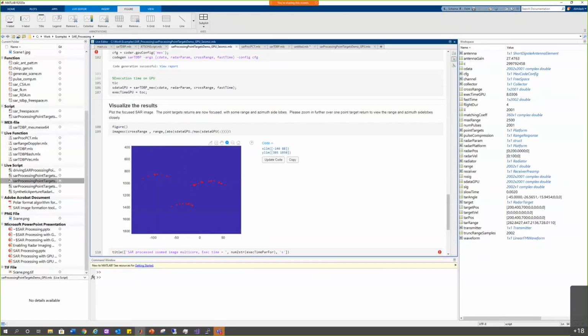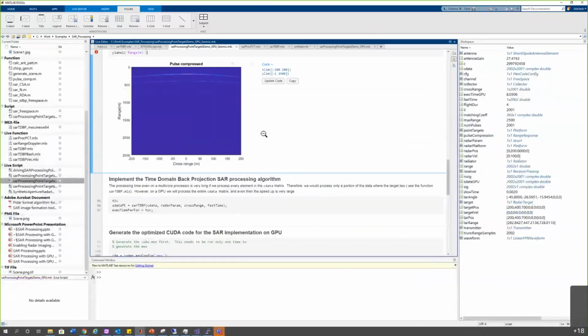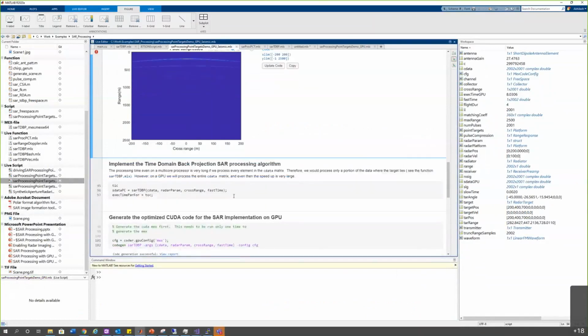And then I will apply the phase compensation for the data points, which is my signal, and then add them up. So that's what's happening. So add them up, add them up, add them up. So that's why when I see this nice parabola, like, the big ones, I actually synthesized a parabola on top of this, and I added all the pixels so that all the data points converge in this nice point targets.